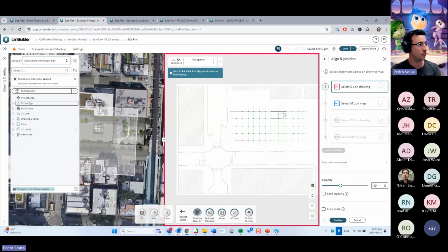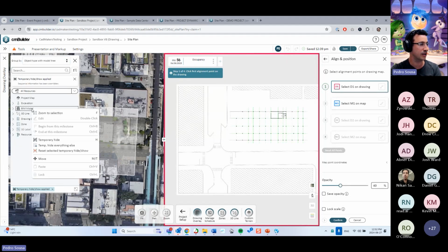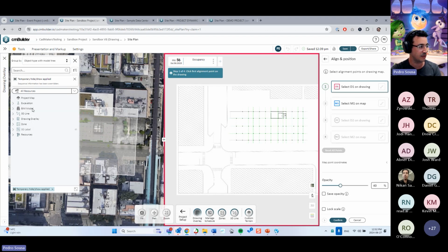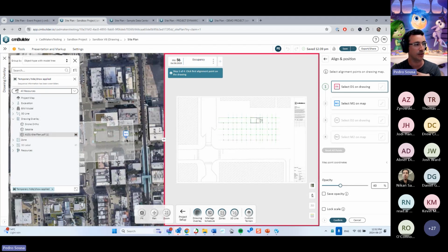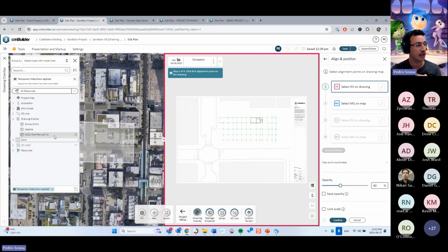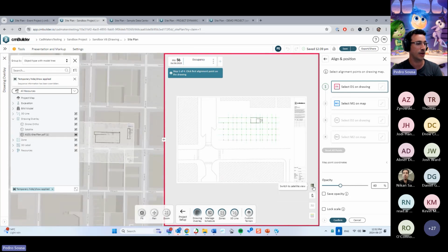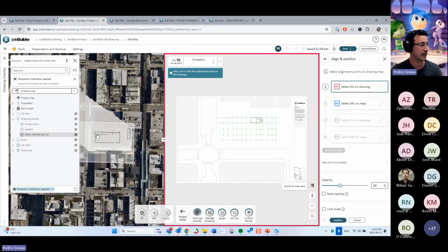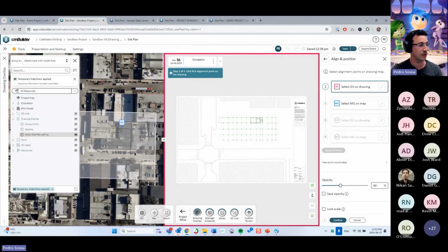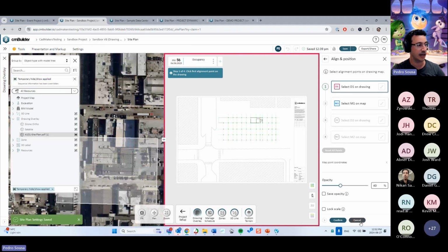And if you select beam model over here and right click, this is not actually selecting the beam model. You see that I'm clicking over here, but it's not selecting the beam model. What is being selected is the element that I'm editing at the moment, right? So if I want to hide everything else and keep only the thing that I've selected at the moment, you can right click and say temporary hide. All the other parts go away, and then you can switch it back to your satellite view over here and do the placement using a clean view.